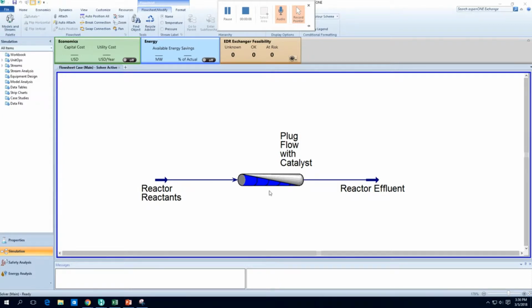Today we want to talk about making the reactors diabatic, which means that there's heat transfer from this reactor. Why are we doing that? Well, there are two reasons basically. One is that diabatic reactors can help increase yields because in this case, methanol reactions are exothermic, so you tend to have a higher yield at low temperature. So you kind of want to cool the reactor down. And secondly, of course, you want to have diabatic reactors because you want to generate steam. Okay?